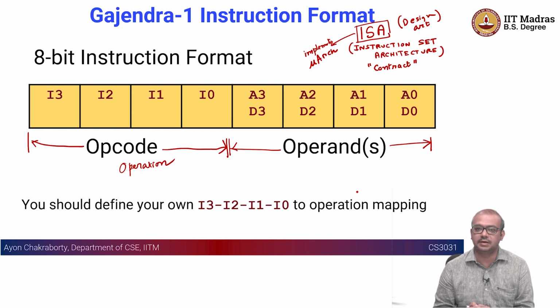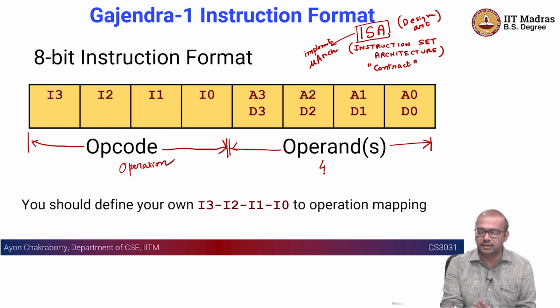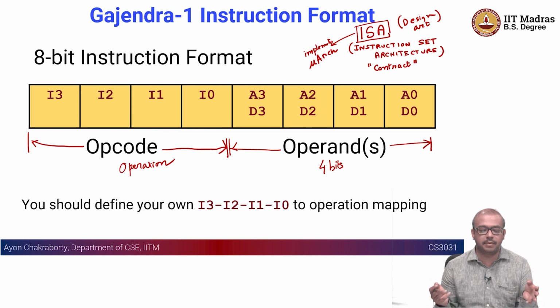In this case, there is nothing but raw bits that you need to pass as part of the instruction, and here we only have 4 bits. We are constrained by this 8-bit instruction format. With a 16-bit instruction format, you could have done a little bit more. Of course, addresses are going to take up a lot of it, because you often need to pass an address.